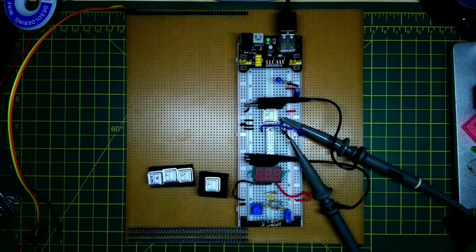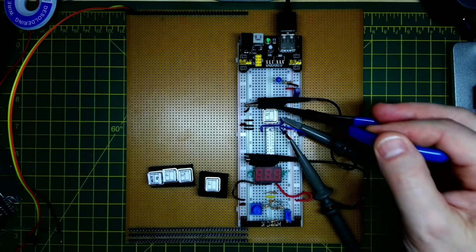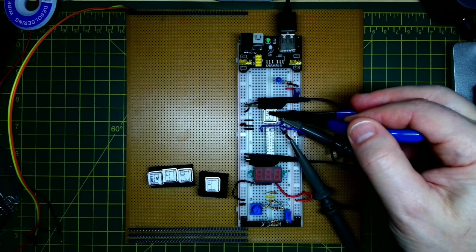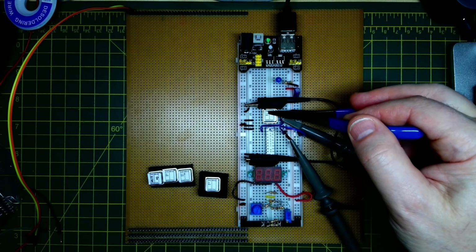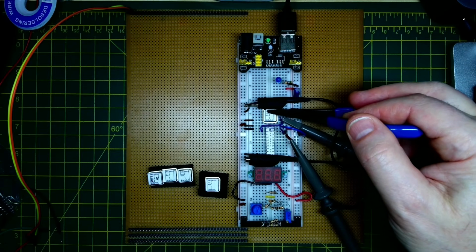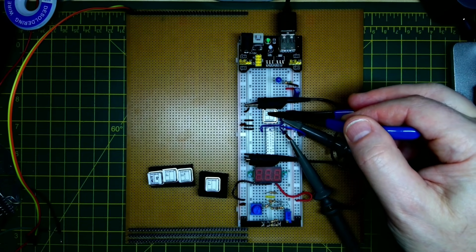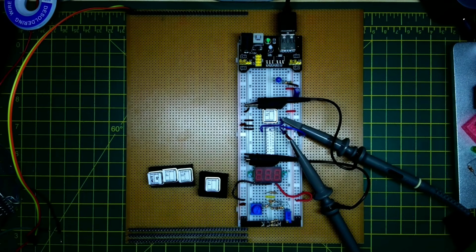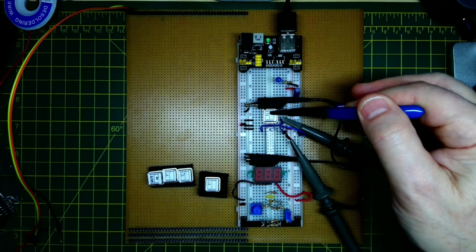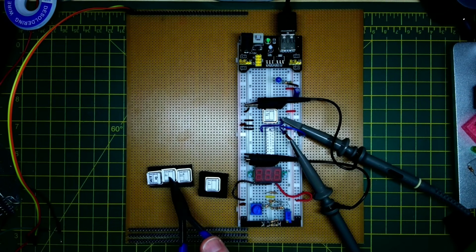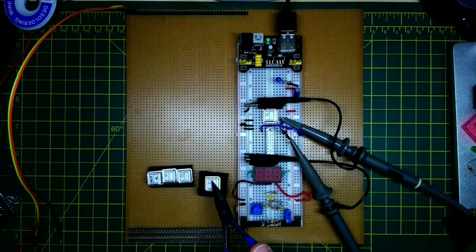All we're going to do is to see what actually happens when we try and shove various oscillator outputs down the bus here. And also I've got a variety of crystal frequencies. So the one here is about 3.68 megahertz, which is the frequency which tends to be used for driving serial ports. So this will do frequencies such as 115.2 kilohertz all the way down to about 9600 baud. This is just under about 4 megahertz. Then I've got 8 megahertz, 16 megahertz, 25 megahertz, which is the VGA dot clock. And I've even got a 40 megahertz one. So we'll see what happens with that one. I'm not expecting that one to be great with this setup, but it's just out of interest.